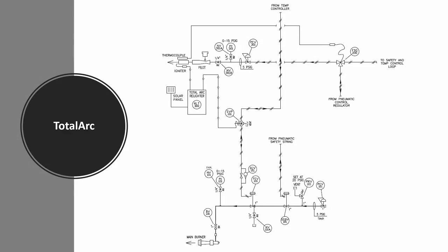What we're trying to do with that is prevent the entry of natural gas into the fire tube. Once the pilot is confirmed to be on, then this valve will be released and will allow this valve to operate as normal.